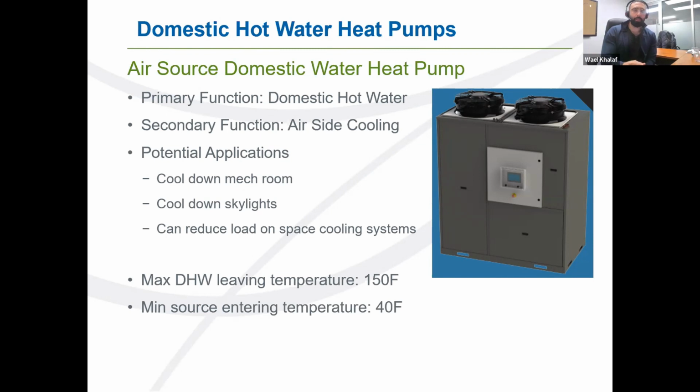hot water for that particular application, and also what temperature you would like to store your hot water at. Most commonly, we see 140, but we've seen some applications where they would prefer to store it at 150 or 160, and that really changes the amount of storage there is. So there's no rule of thumb really.